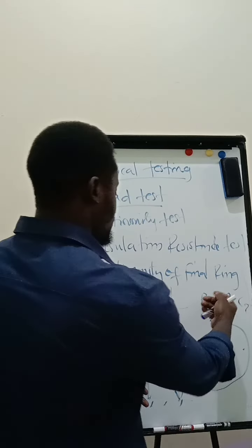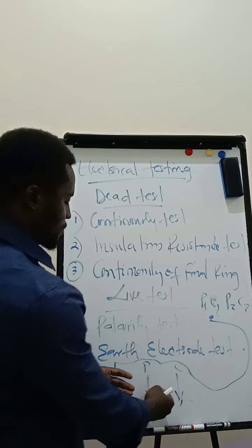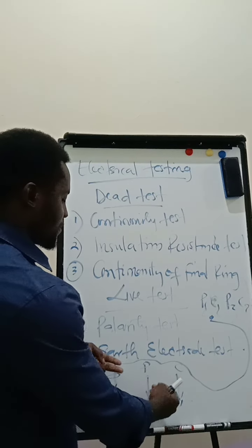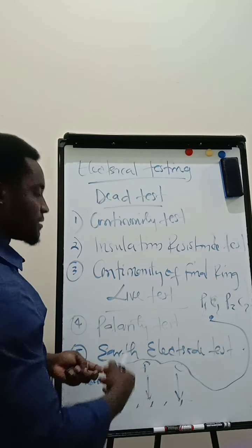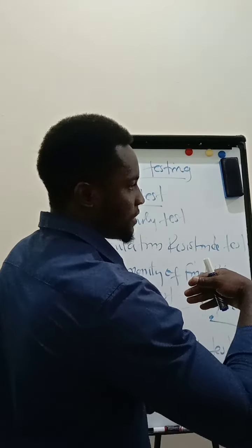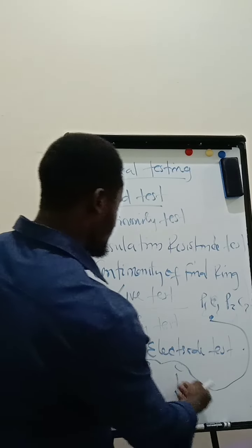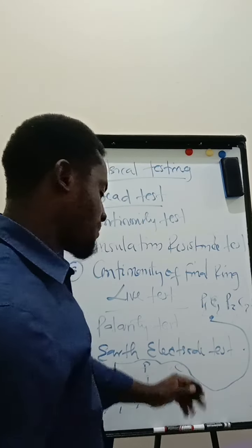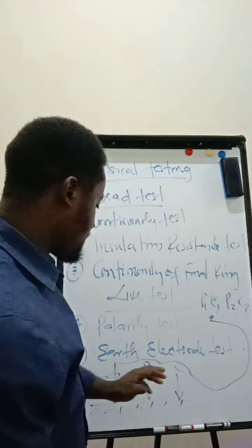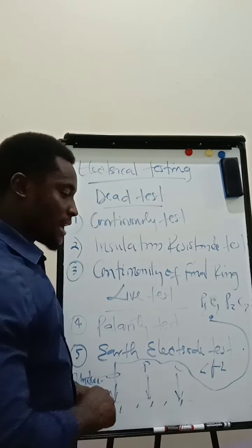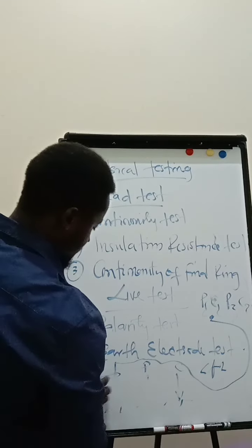After putting this, we take down the first reading, and then we reduce the distance by maybe between 3 meters to 5 meters, and bring it closer to the electrode under test. We take another reading, then we take it behind as well, between 3 to 5 meters again, and record another reading. Then we take an average of these readings, compared with the different readings, to ensure that we have an earth resistance of less than 1 ohm, which will be accepted by QCS 2014.